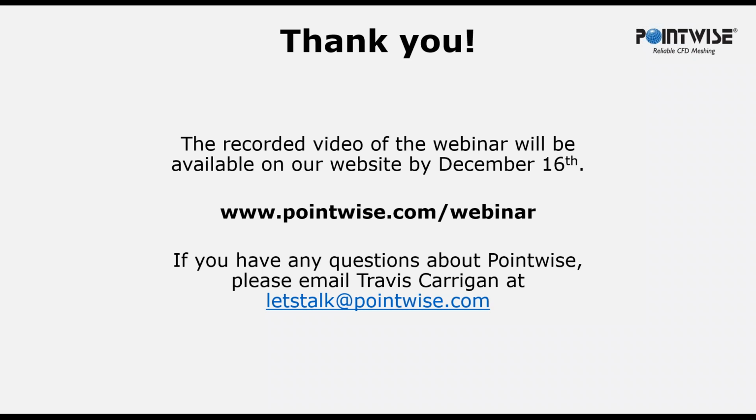All right, our third question is about sources. Will grid sources affect the domains and connectors that they encompass? If so, is it better to initialize the domains and connectors after setting up a grid source? This is also a very pertinent question and good. Right now, grid sources are just going to affect volume cells. We realize how desirable it could be to have them also affect the connectors and domains they encompass, but that part of the feature is not really quite there yet. We certainly hope to do so in a future version. If this is something that you're very interested in, please email us at support@pointwise.com and we will make sure we add you to that feature request so that you get notified when we have that capability.